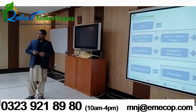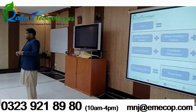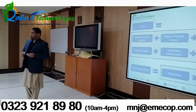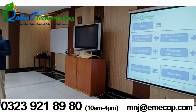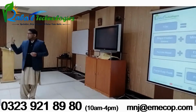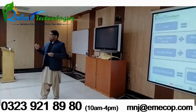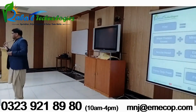If the manufacturer is professional and technical, they will ask you what your duty point is. So you must know what a duty point is. The duty point is the point at which you have designed your system for 2 parameters. Number 1 is head, number 2 is flow rate. So you have to give the manufacturer 2 parameters: this much flow and that's my head. Please suggest me a pump.